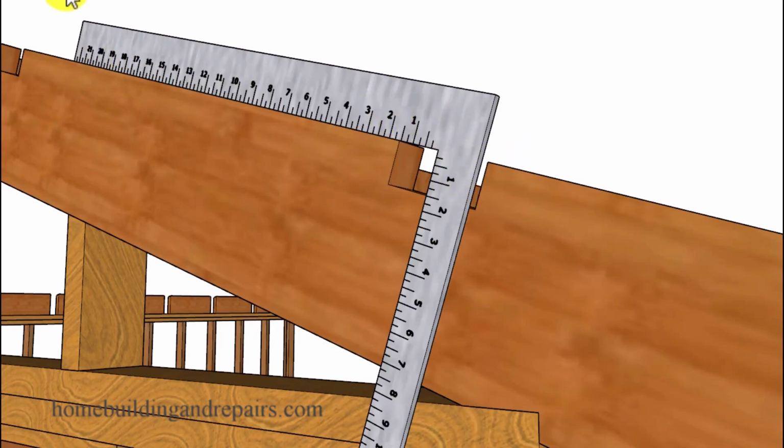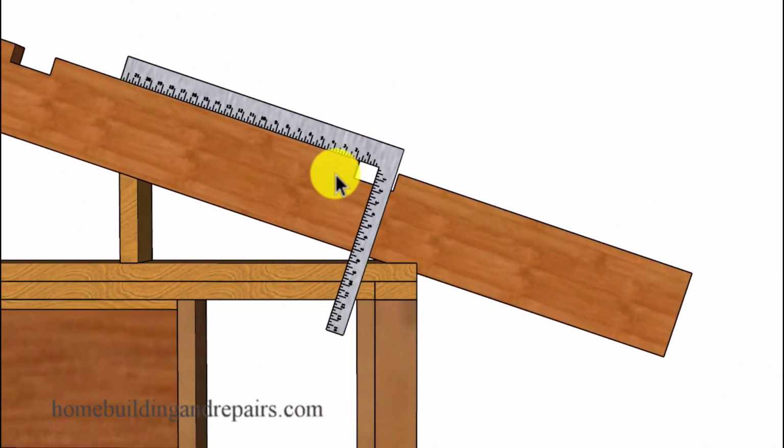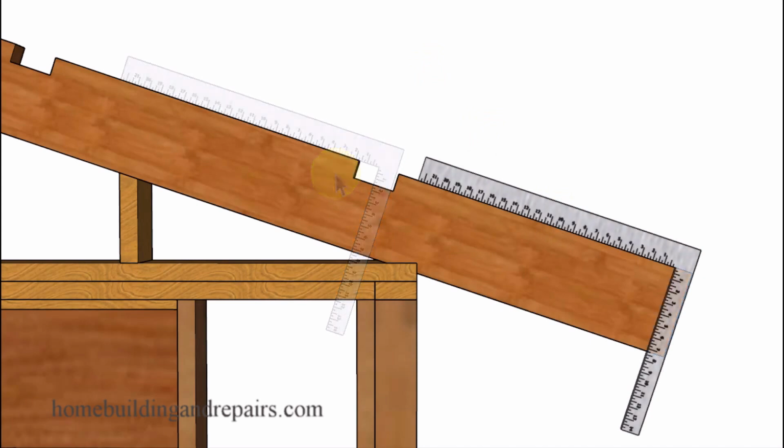And these notches are normally spaced 32 inches apart. However, yours might need to be closer depending upon whether or not the fascia board is going to be larger, or the distance from the fascia board might be a little further out, or you might be installing heavier roofing materials like roof tile.